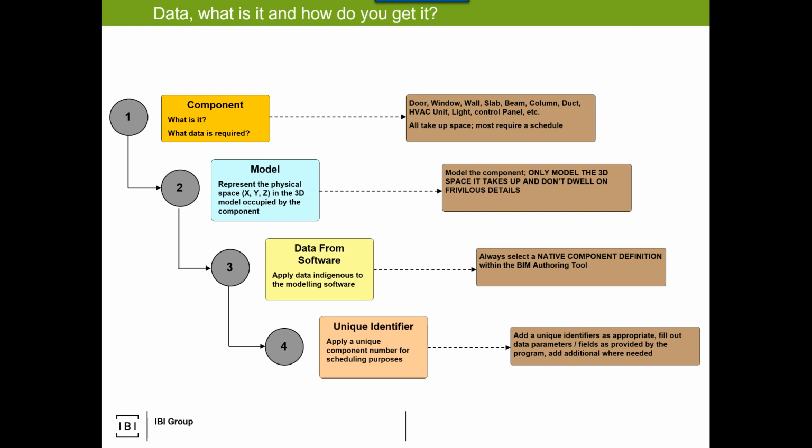And then the concept of unique identification. This is an important thing because it starts to open the door to the other BIM users. If we're analyzing, we may need to ensure that the beams and columns are identifiable from each other. Definitely doors and windows need a number. Oftentimes equipment needs an identifier. Now, if you're in the world of Revit or ArchiCAD and we go through the IFC file, every single item is uniquely identified by a 64-character GUID. So that's good, but oftentimes we don't want to go through GUID mappings to find all the GUIDs that represent my doors. So therefore we apply door numbers. Unique identification. So having a strategy around that.